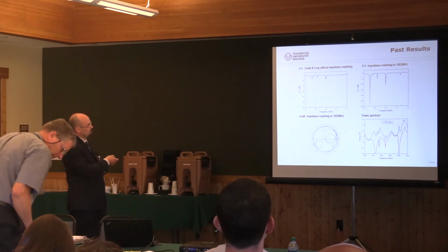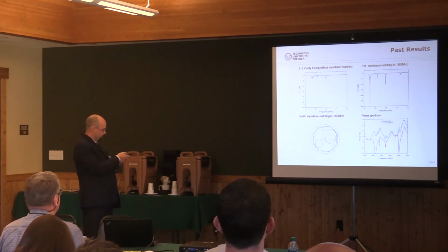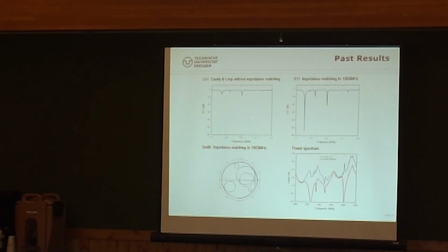So I tuned the cavity with our three-step tuner. You can see here the often asked for Smith chart. The matched frequency at 1863 is almost exactly hitting the 50 ohm point. And as a result of this matching, we can see a power spectrum done on the balance. Here you can see the unloaded Q factor if you want to calculate it. And from this power reflection minima, you could calculate your loaded Q factor.